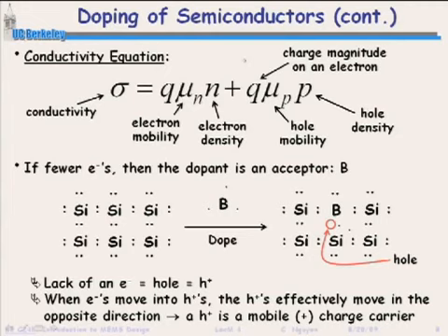Well, if you dope the silicon with boron, for example, which has 3 electrons, so 1 fewer than all its silicon counterparts, boron's going to fit in here, but this is now going to look like a missing electron. This missing electron allows other electrons to go into this hole. So you think of this electron going to that hole, well, that creates a hole right here. Then another electron here goes into that hole, that creates a hole like here.